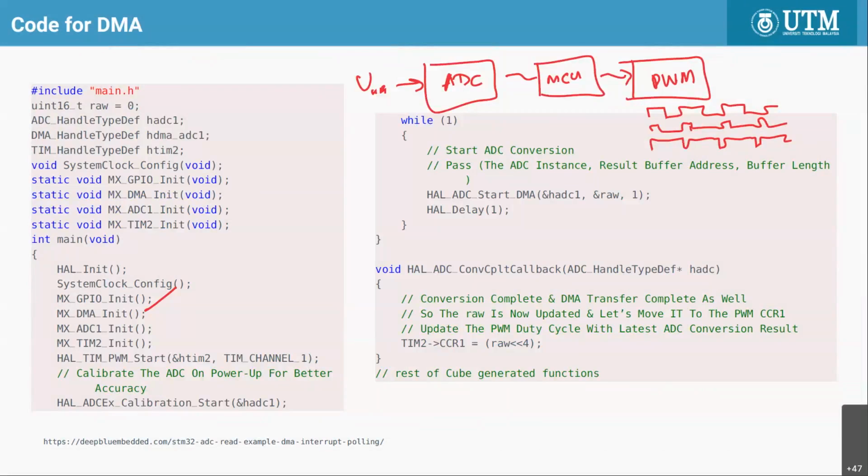So PWM can be sort of a digital to analog. Okay. So what this example is doing is read data from outside, convert to PWM. So higher voltage here will be longer time on and shorter off. If you put the value low, then a longer time off, shorter time high.